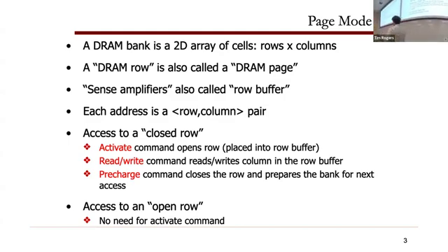When you access a DRAM, it's not like an SRAM where you just give it an address. You have to do it in multiple cycles. You first send a row address, and there's a long time to turn on the row, and then you send a column address. So there's these things called RAS and CAS. You probably have seen these before if you've talked about DRAMs. Row address strobe, column address strobe. These are timing numbers on how long it takes, once you send this command, for it to actually do that particular operation. So when the memory controller is spitting stuff out to the memory chips, it's going to have to first send a row command, light up the row, and then it's going to have to send several column commands to read each of the columns.